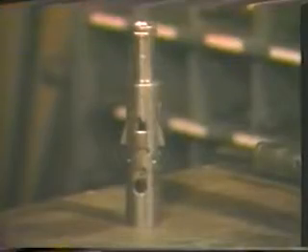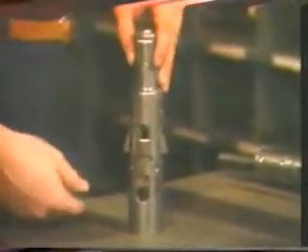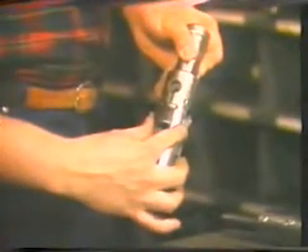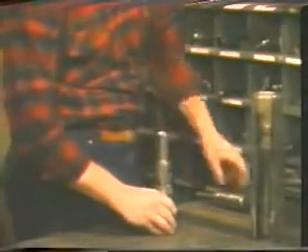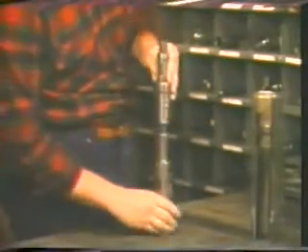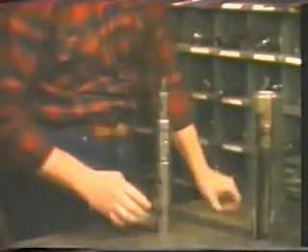The Baker selective lock is called the S-lock assembly. Two of the locking dogs face up to support any pressure differential from below the lock, and two dogs face down to support any differential pressure from above the lock. The simplest and most often used running tool is the C1 running tool. It is pinned to the S-lock by two sets of tangential shear pins.